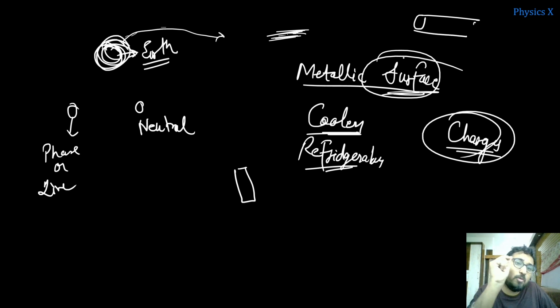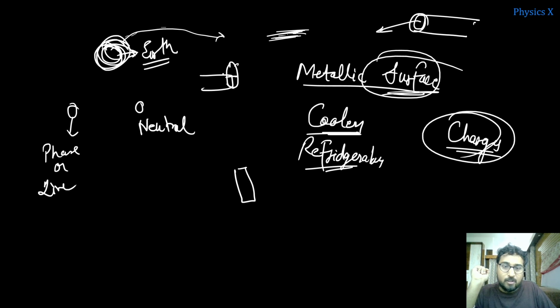So what happens as you place this into the socket? First contact comes through this pin only. As you place the plug in the socket, the first contact is made by this longer pin, which is earth. As soon as this earth gets connected with this socket, these extra charges will first flow through the earthing mechanism and they will flow to the ground.